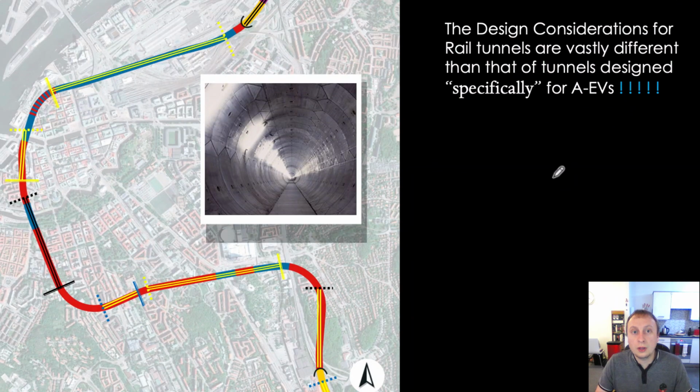So that's all well and good, but remember we've still got our issue with the curved parts of the tunnel alignment. We're not going to bother using hexagonal segments in the curved sections. It just doesn't work. It's too difficult to play around with these segments the way that it lines up for curved elements. So what I'm going to do is introduce a bridging piece. I'm going to explain that in a moment. Let me draw that again.